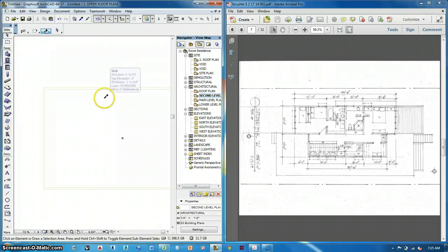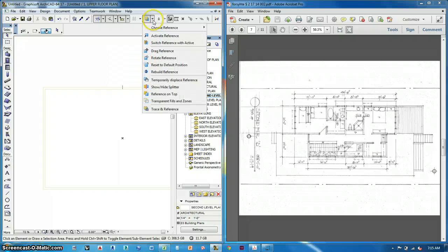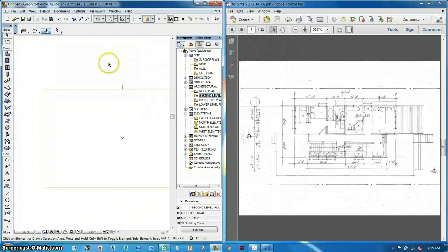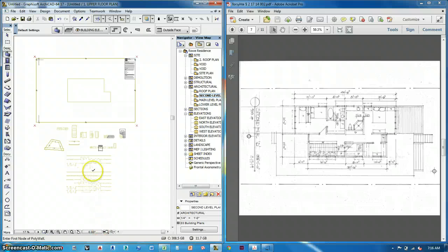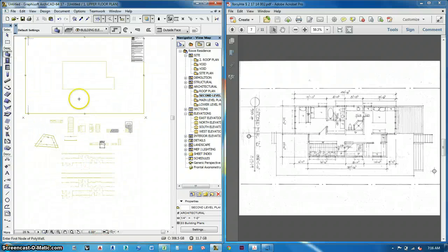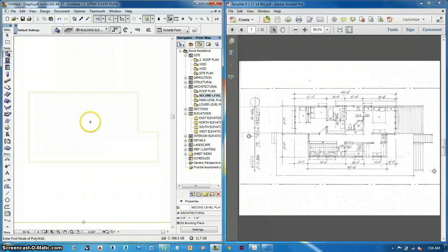What I want to do here is, with my mouse wheel zooming in, I'm going to hold down the Alt key, which gives me the pick tool. And you can see when it fills up, when I get over something, it's telling me that I'm over a wall. That's the wall down below me, right? Because my reference, I can choose a reference below current story, and I can pick that wall. So now I've got the same wall on the upper floor. I can also go down here and pick those walls too. They're all down here, which is why those walls are really modeled on the main level, so that we can have them as a reference level. The basement level, they're different walls, so they're different. So I can do that, and I can do my little trident.